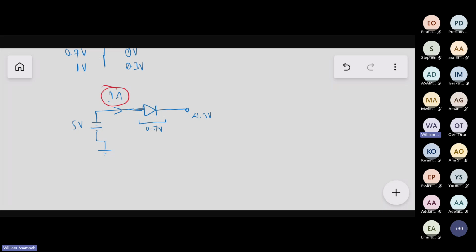Then you just go to Google, Gemini, or whatever, and search what diodes can pass 2 amperes of current. Then it will give you some part names. The next thing to look at is the maximum reverse voltage. If you are connecting it to the mains, you know that the maximum voltage of an AC current is 325 volts.